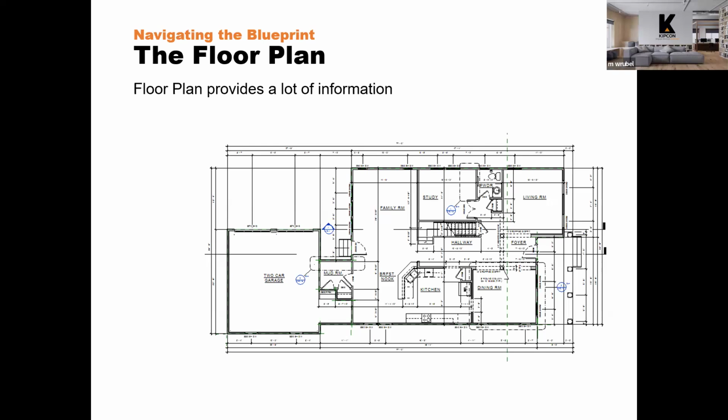It might say on an architectural plan, 1/4 inch equals 1 foot, or 1/8 inch equals 1 foot. Or in the case of a site plan where you've got much larger scales, it might say 1 inch equals 50 feet, or 1 inch equals 20 feet, something to that effect. On an overall layout plan, you might see 1 inch equals 100 feet. So these scales are obviously not true size. They're proportional to what's going to be built, but they're scaled down versions of it.